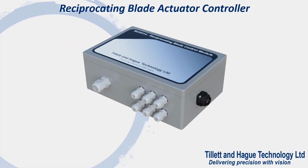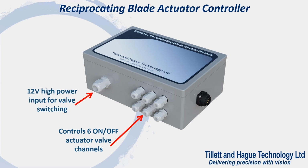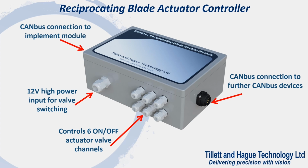Similarly, this is a reciprocating blade actuator controller. It also has 6 valve output channels, but has no sensor connections as reciprocating blades operate without feedback. There is a gland for an additional 12 volt power feed, which is often desirable as the valves may require more power than can be delivered via the CAN cable. Like the hydraulic rotor module, additional controllers can be connected in line to provide more output channels.